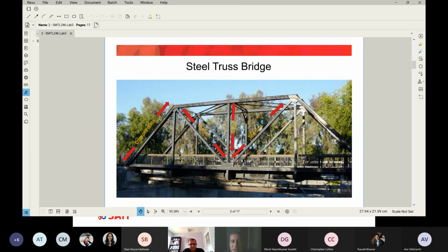So for example, this is a steel bridge, very, very common, not for cars, but typically for railway and for sea train. For example, if you go to the southwest of Calgary, you will see a couple of those in the southwest or southeast. It's called a truss bridge. So it's made out of steel members, like we call them top chord, bottom chord, diagonals and verticals. And I just want to make sure that you understand these members, you can see I labeled them with the forces in them.